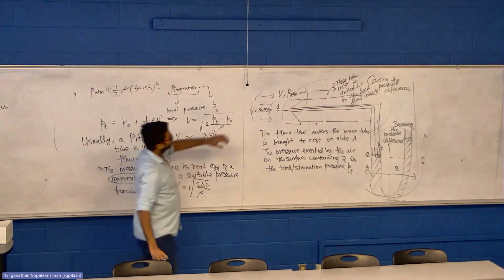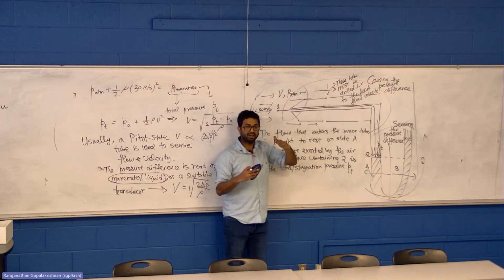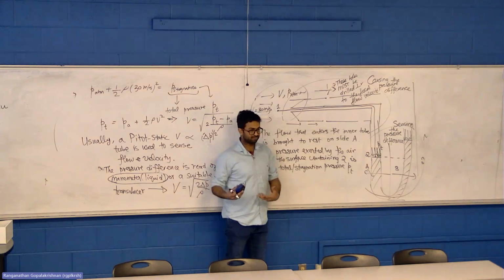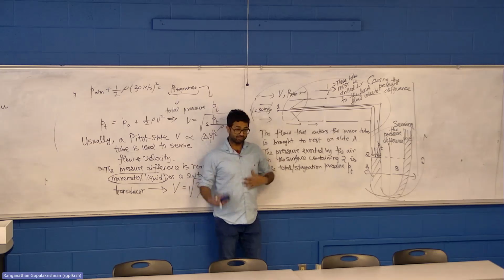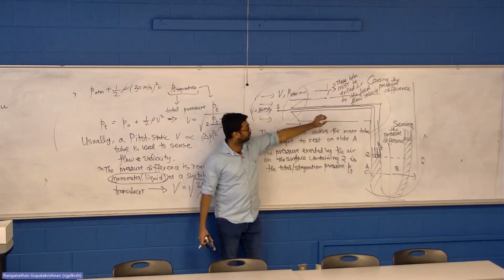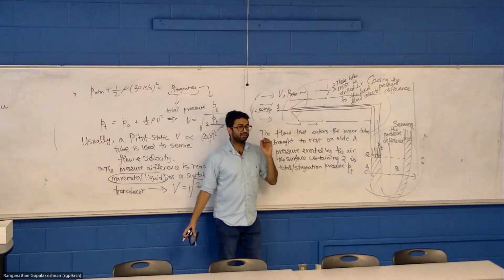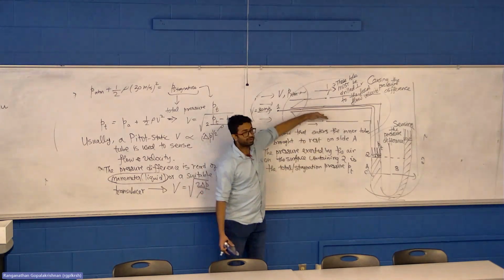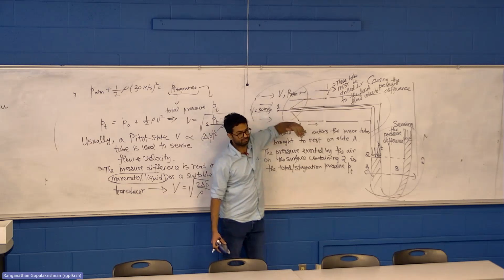You want to isolate the molecular motion in this pressure that you are trying to sense. And if you have it at any angle other than 90 degrees, you will have some bulk kinetic energy contribution as well, which you don't want. Is that making sense? So this might sound like a very academic thing, but when you are actually using a pitot tube to read a flow velocity, or you're mounting it as a sensor in your bigger system, the important consideration is you have a sense of what is the local flow velocity and mount your sensor so that these holes are exactly perpendicular.